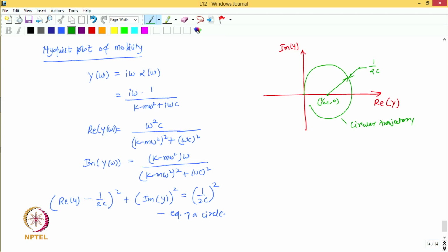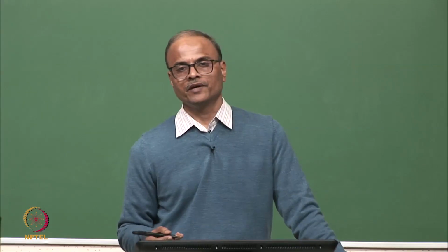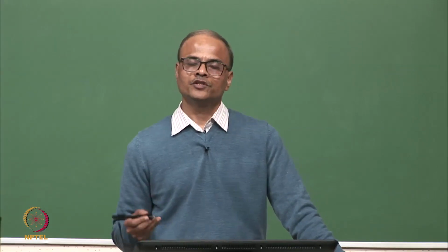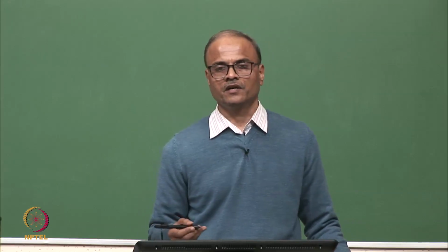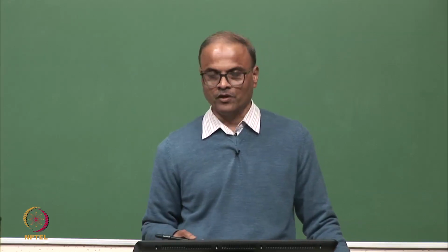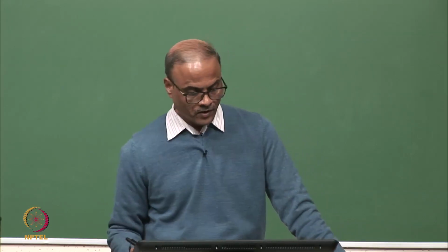So, this is a very important property of the Nyquist plot of mobility for a single degree of freedom system with viscous damping, and later on we will make use of this property in one of the methods of modal analysis. There we will see how this property is used to determine the modal parameters.